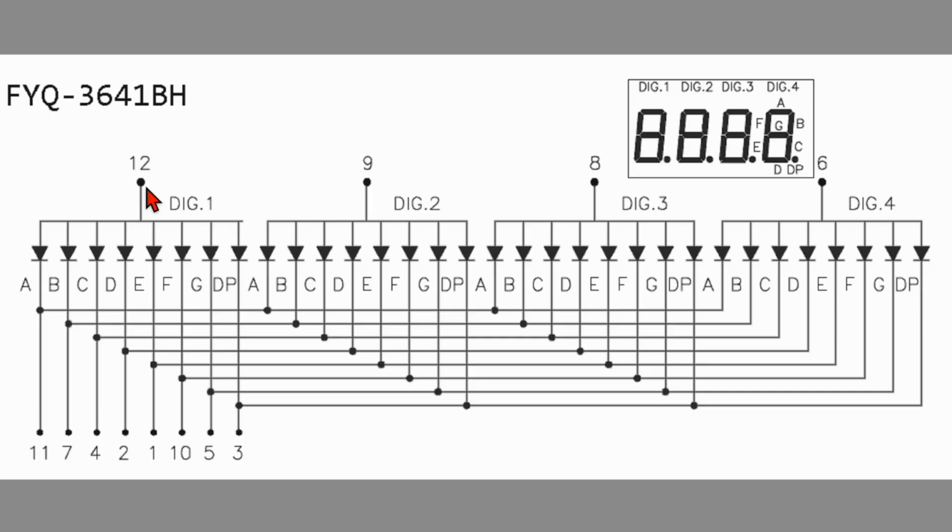So what we're going to do is put resistors on the digit pins. We'll use 4 resistors, 1 on each of the digit pins. I suppose we could put the resistors down on the segment pins, but there are more of those, so it makes more sense to put the resistors on the digit pins. We can use a 330 ohm resistor. That's appropriate for an LED with a 5-volt power supply.